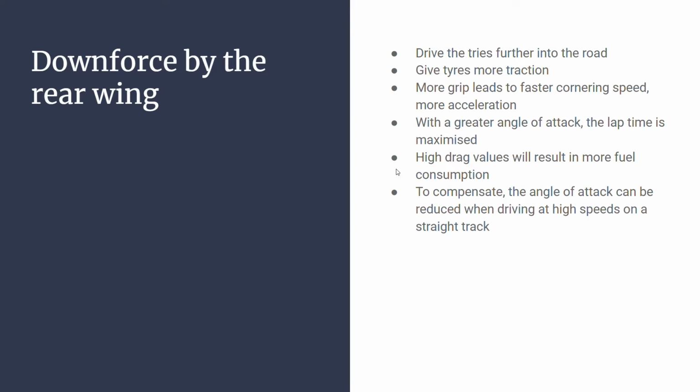However, due to high drag values, fuel consumption also rises. To compensate for this downside, when driving at high speeds on a straight track, the angle of attack can be reduced, minimizing downforce and drag. As a result, fuel consumption will be reduced.